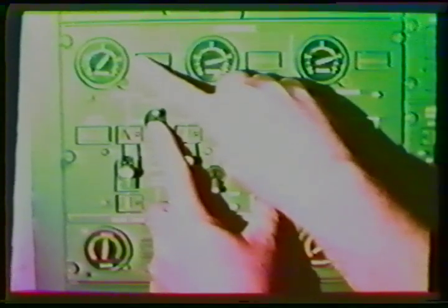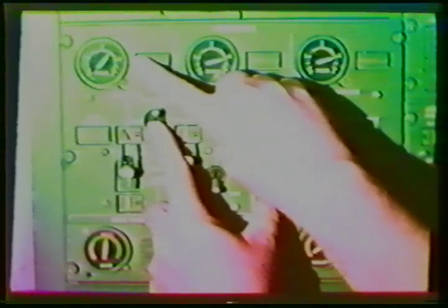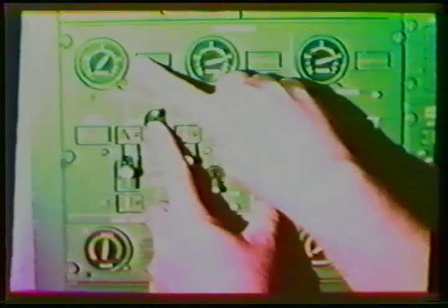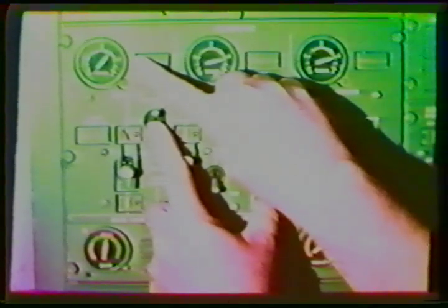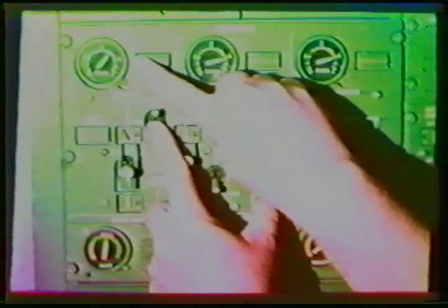Here is an example of a PTU being used for auxiliary power. Assume an in-flight situation wherein the blue system pump has been put to dump as a result of a malfunction. Subsequently, the left PTU was turned on to power the blue system components. Again, note the pressure of 2,500 psi on the blue system pressure gauge.